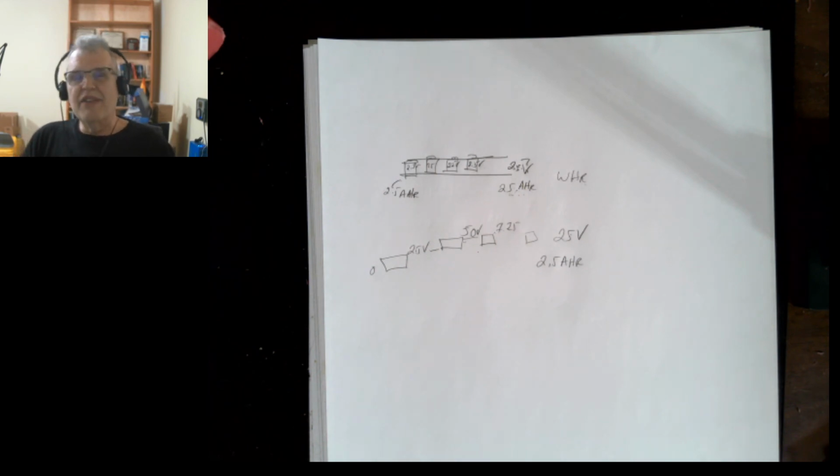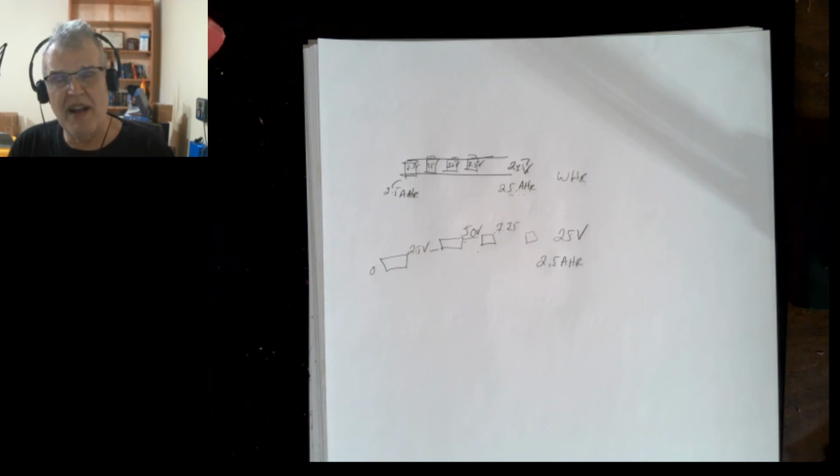What am I going to do? I'm not even sure yet. I keep going back and forth. I keep thinking, well, I could do 7S. It would be easier for my BMS, and we'll get into that in a later video, because then I only need 7 different packs in series to make up my battery. But by the same token, maybe I'm going to go 14S and get to 48 volts. I'm looking to get something around 15 kilowatt hours for the energy capacity of my battery. I'm not exactly sure what I'm going to do, but I'll have to figure it out pretty soon because I processed a lot of cells and it's getting time to do it.